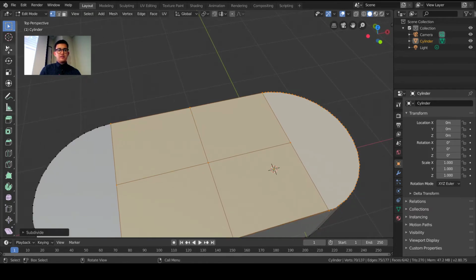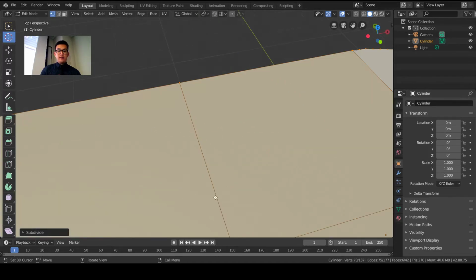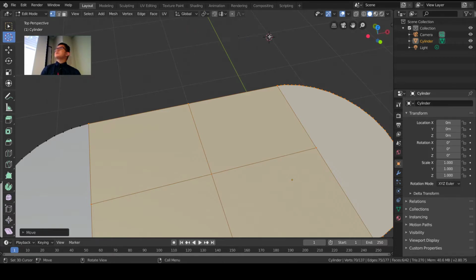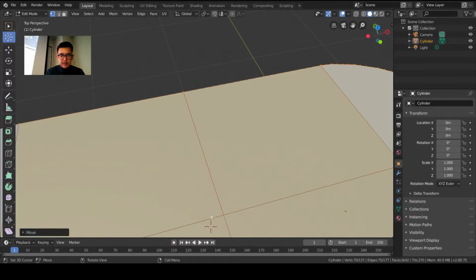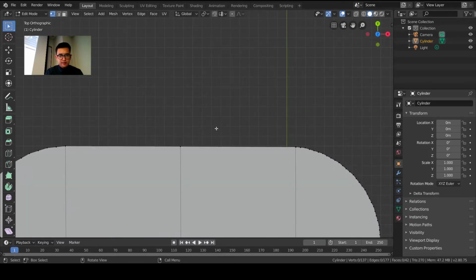So the 3D cursor tool is just the second tool from the top here. So I'll click that cursor, and anytime you left click when that's selected, you'll be able to specify a new point for the 3D cursor, just like that. And if I want to set the 3D cursor exactly to the point in 3D space where this vertex is, you can see if I just try clicking it, it gets close to it, but it's not precise. So the best way to do it is to deselect everything by clicking off. And let me go back to a better perspective.